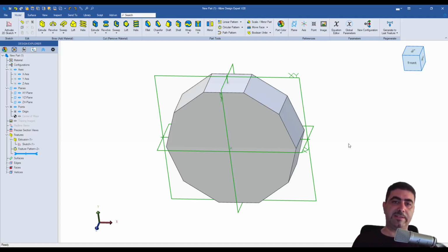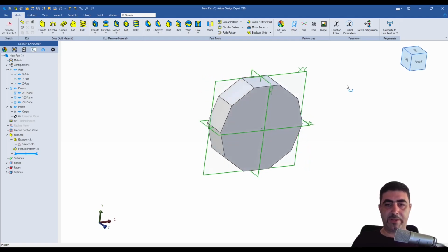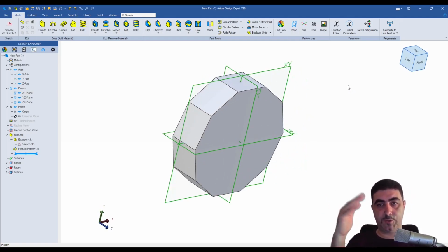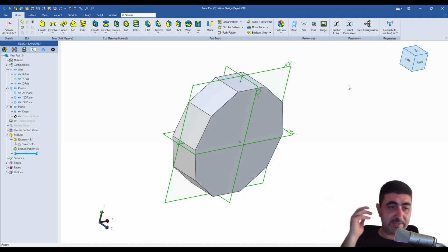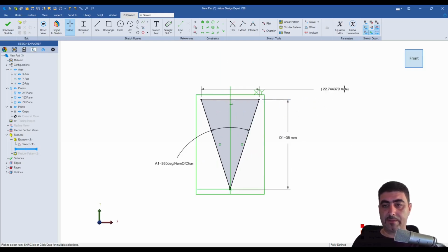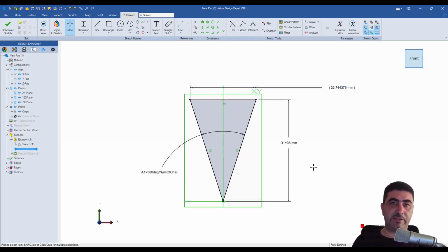If you also wanted letters here, you would need enough sides to put in all the letters and numbers. You need 10 sides for the numbers and 26 sides for the letters, so you need 36 sides. Then you would go in and tweak this number to get roughly the size that you need up here. For reference, for 36 sides, I have calculated that if you do around 120 millimeters here, it should give you around 20 millimeters of length per side.